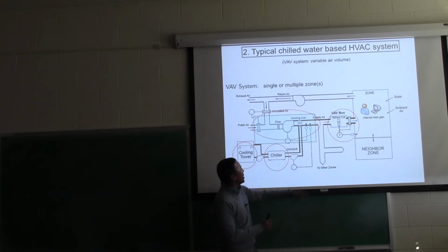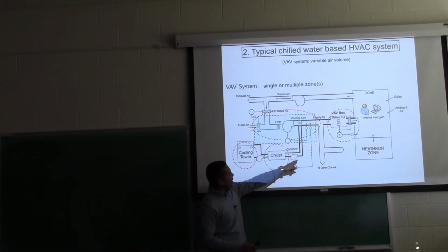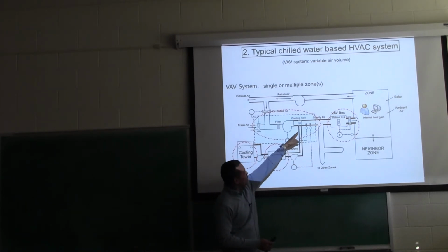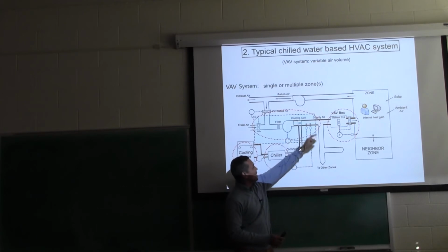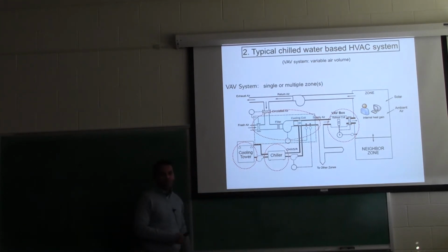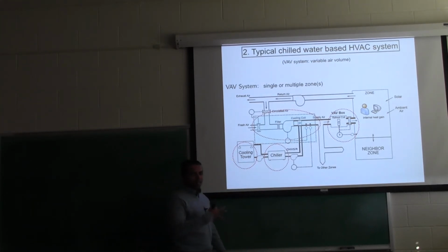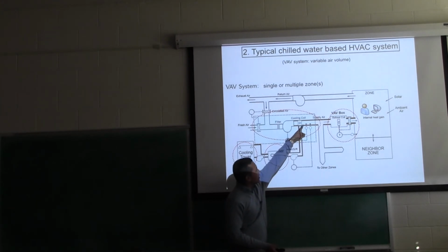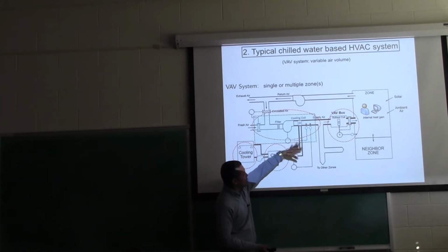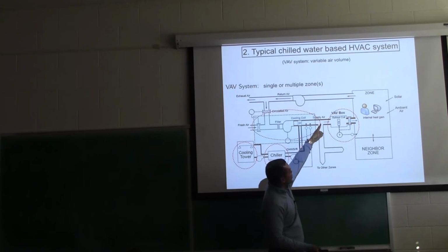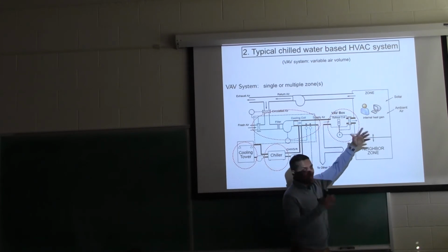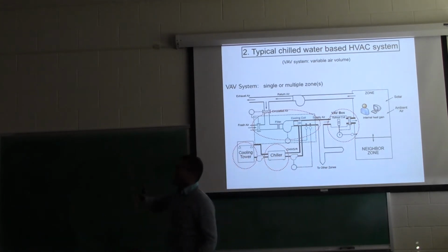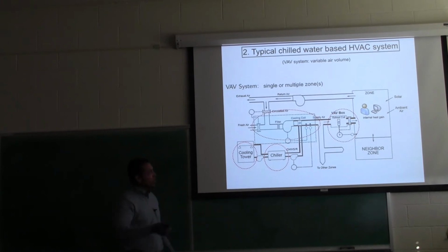That happens in something called a cooling coil. In the cooling coil, there are control loops that look at the temperature of this air and try to maintain that temperature at 55 degrees Fahrenheit, so that the air is cold enough and dry, all of that. It's controlled by controlling the flow rate of the chilled water. So all that happens, and then you get cold and dry air that goes into various zones. A zone, you can think of it as a room, like this is a zone maybe. Or maybe 2 of these rooms are a zone.